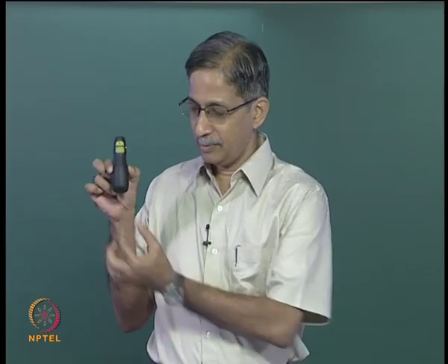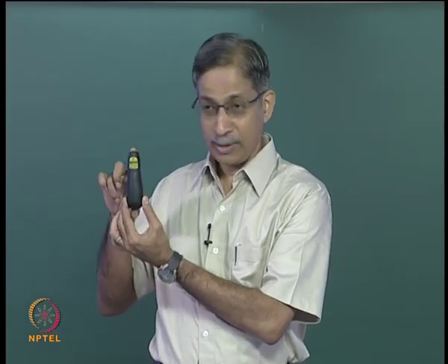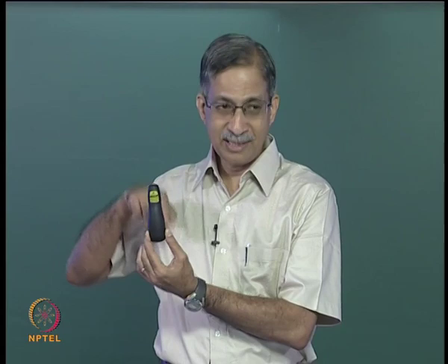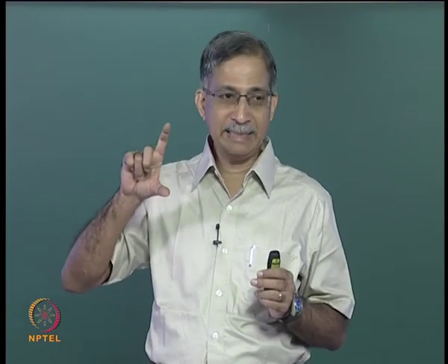Now if the shear wall is slender, in the sense that the width is small and the story height is large, and there are many stories, then essentially it's going to behave like a flexural element. Okay, the deflection shape will be like that, right? But sometimes you encounter shear walls which are very wide and stocky and the height is less.